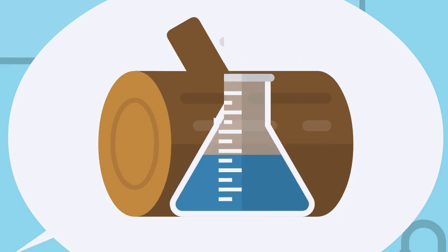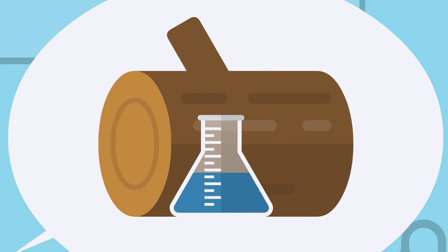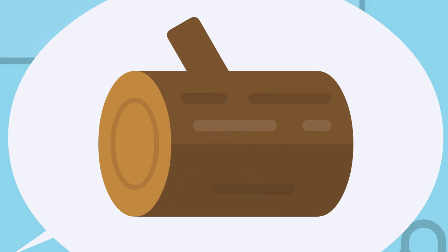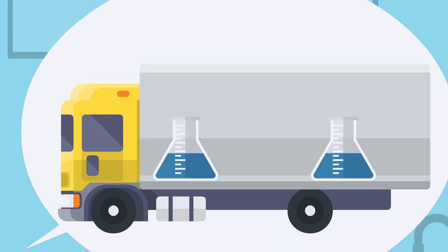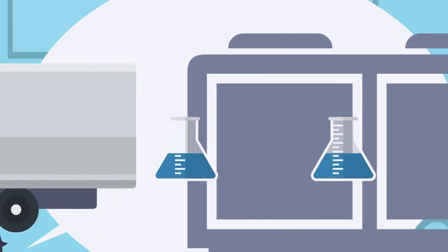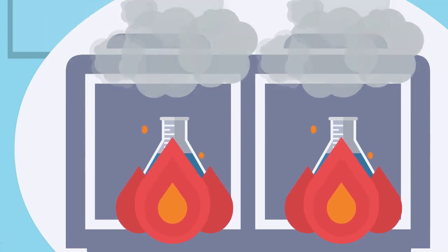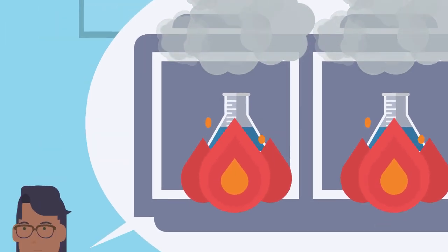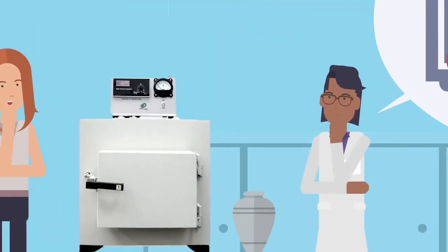After several months of storage, biomass loses water, and when you receive it to be burned in an oven or boiler, the moisture content should be low for an efficient combustion process. Water is an extra weight you are paying to be transported to your boiler, where it consumes energy for nothing. So, the less moisture, the better, I understand that.